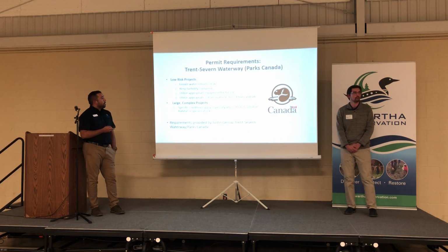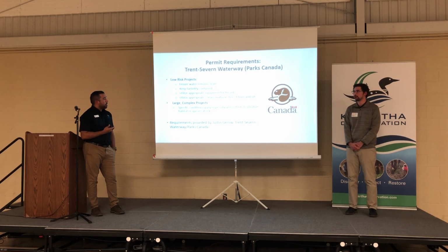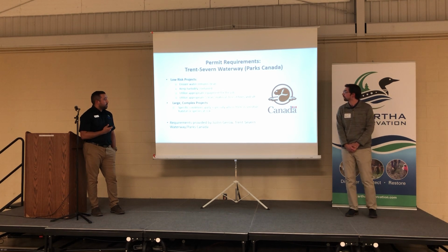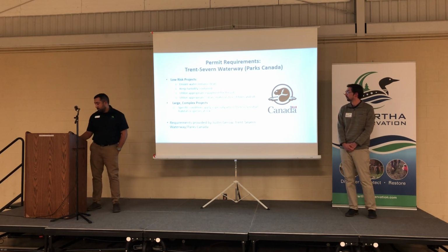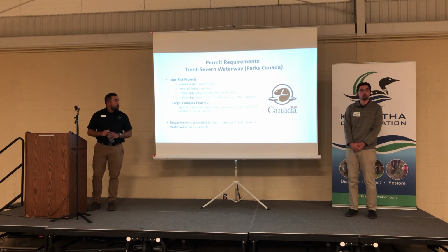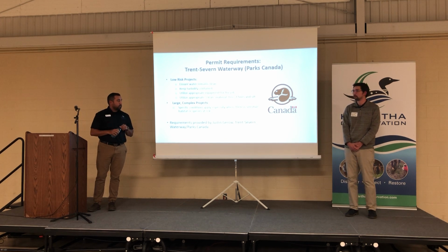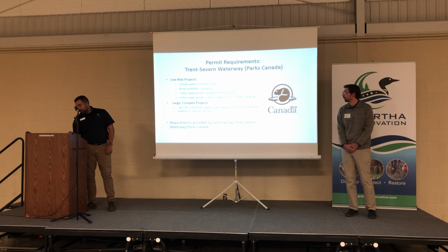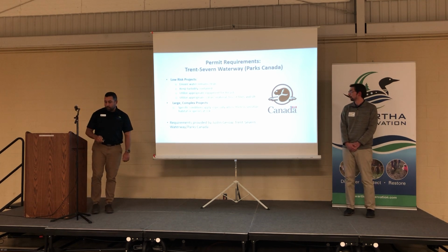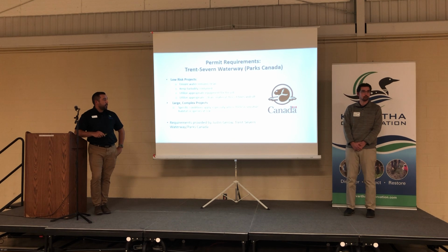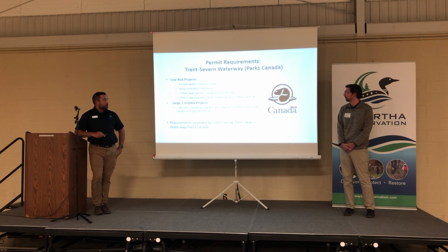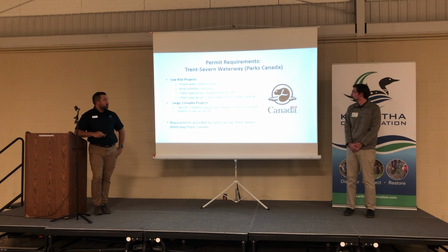So there are a number of other provincial or federal agencies that you may require permission or approval from before beginning your proposed project. For example, the Trent-Severn Waterway, Parks Canada, would require permits or approvals for in-water works. For low risk projects, generally their requirements are that water remains clean, turbidity is contained, and appropriate equipment is used for the job. And with any other permit application from the Conservation Authority side as well, appropriate materials are clean and free of fines and silt. For larger complex projects, there would be specific conditions assessed on a case-by-case basis.